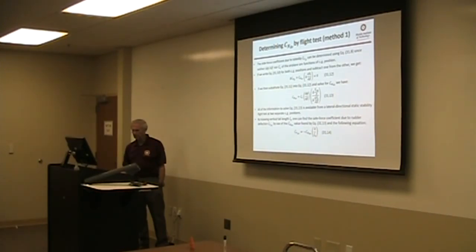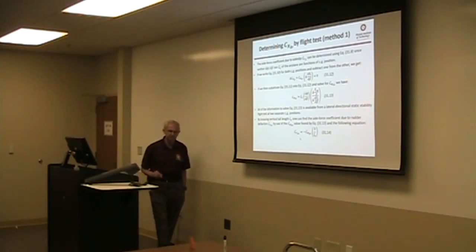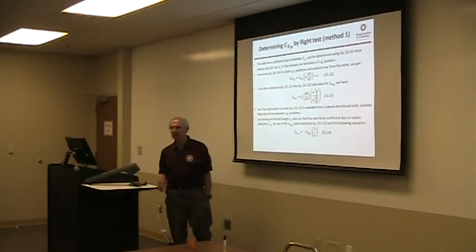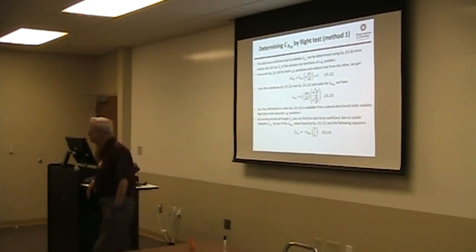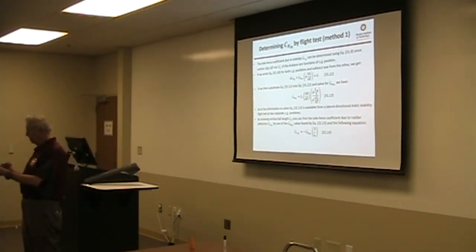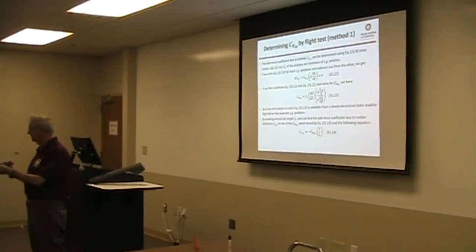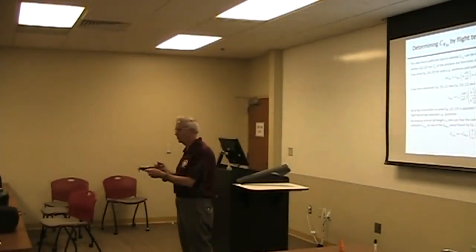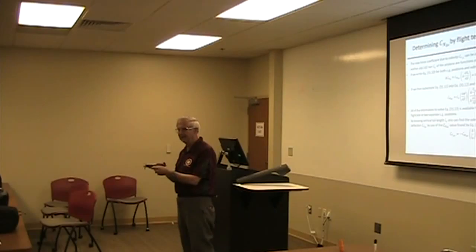These are known values, and we can come up with the side force that the rudder, the vertical tail generates. Essentially, that's what this is. The vertical tail generates lift in this or this direction, whichever way you deflect the rudder. That's a side force. That will actually tend to move the airplane sideways.